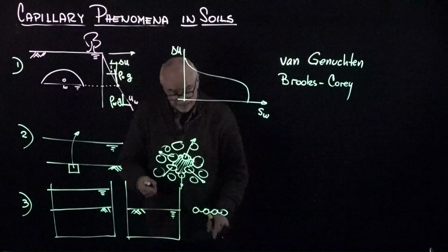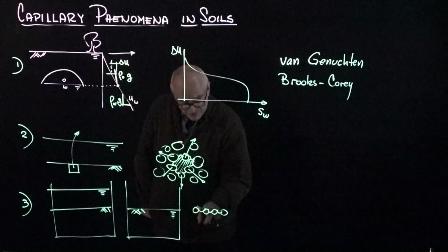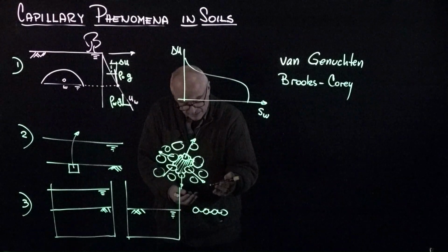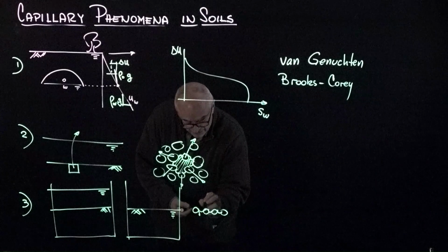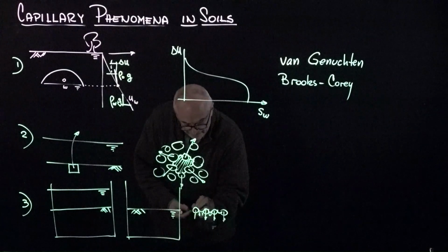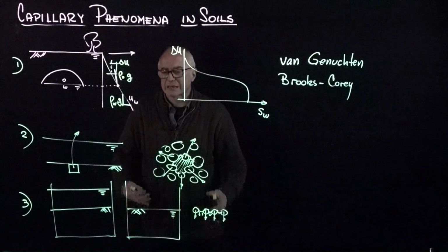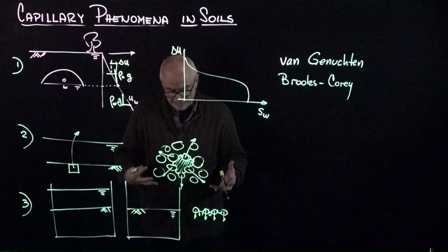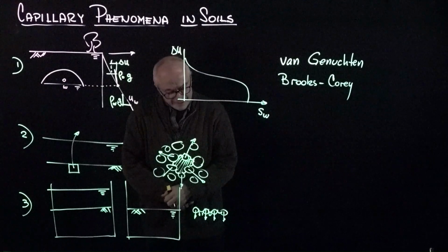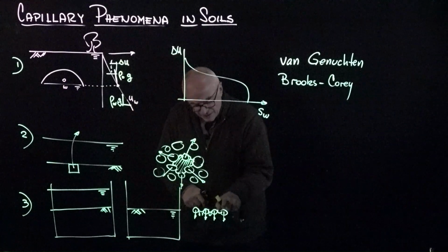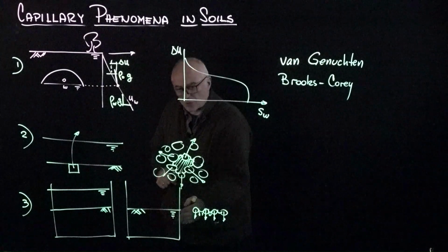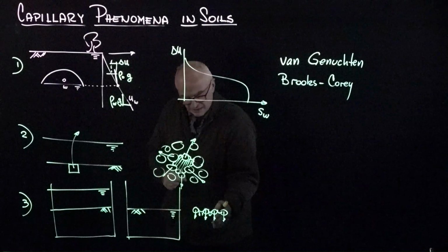Now, once again, this puts the water in tension, and so the lower part of these particles experience the suction compared to the upper part. Furthermore, they also have the interfacial tension pulling them down, and so every particle wants to go down. And this produces self-compaction, consolidation of this sediment, driven by the suction of the drying soil. Now, remember that all these curvatures have to be the same because the negative pressure is communicating through the liquid phase, which is still continuous.